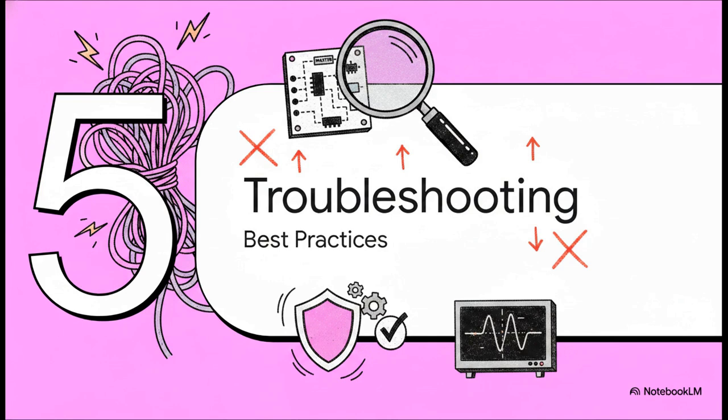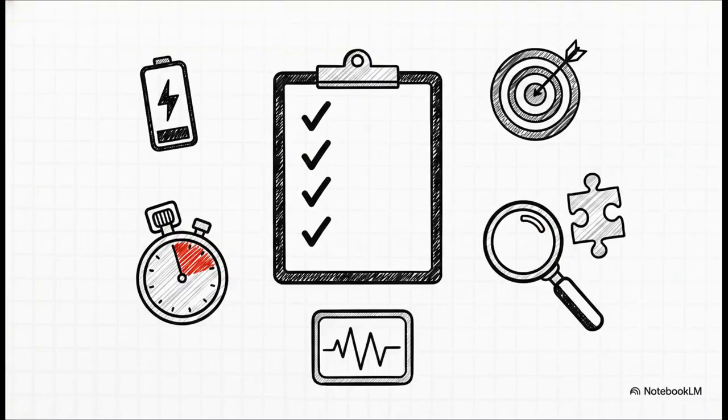And that brings us to our final part, Section 5, bringing it all together, troubleshooting and best practices. This right here is the insider knowledge. These are the exact traps that catch every single embedded developer during a new board bring-up. When a new SPI device doesn't work, do not panic. Start with the basics. Confirm your power, ground, and logic levels. Verify your chip select actually goes active and only selects one device at a time. Double-check your SPI mode and clock speed against the datasheet. And pro tip, always start with a slow clock. Try to read a known static register, like a device ID. And finally, always inspect the traffic with a logic analyzer before you start tearing your C code apart.